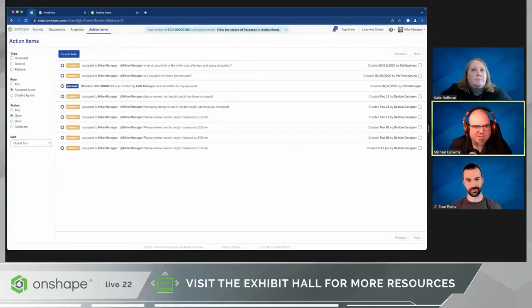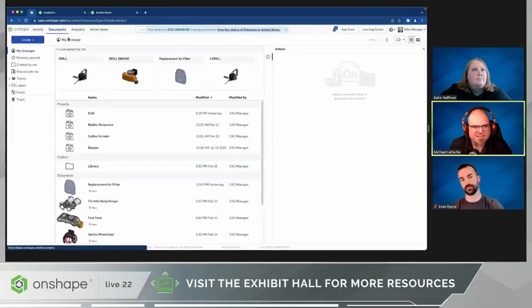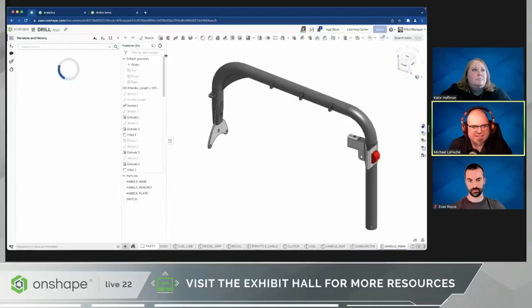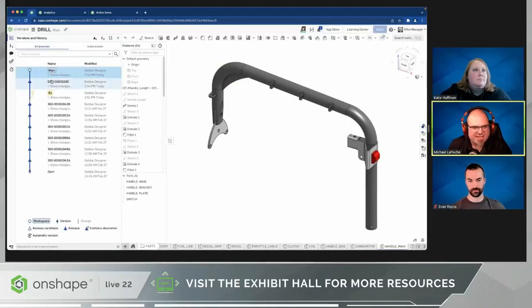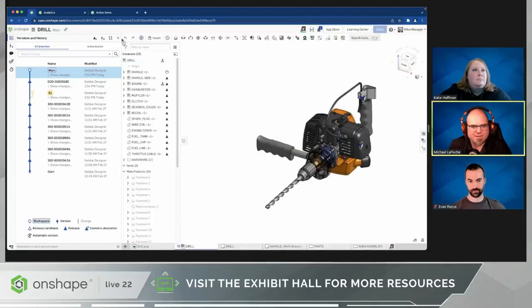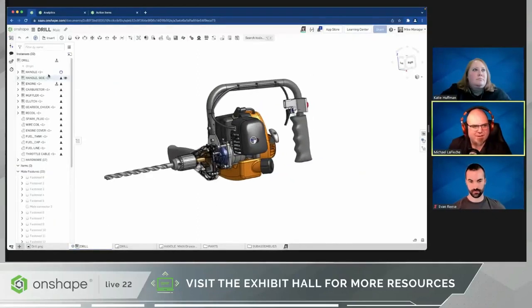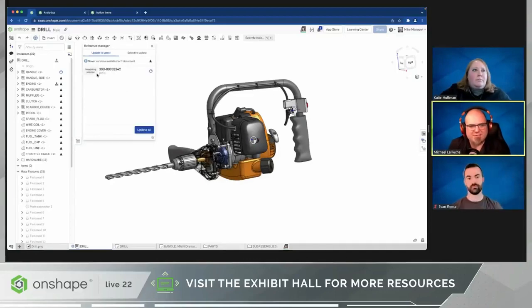And of course I could go to the actual assembly as well. We'll just go ahead and open up the drill here. I can see that the action is going to be all set here. There's the ECO Rev C right there for me. We'll just go ahead and open up the top level assembly here and notice what happened, right? If we look at this, we can see that the handle has a notification message. So we need to just go ahead and update that to use the latest revision of that particular design. So just get that Rev B to C. Couldn't be easier than that.